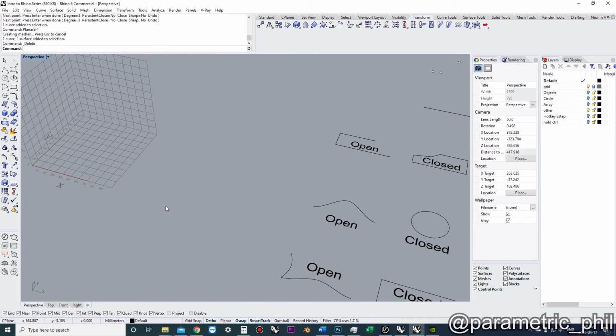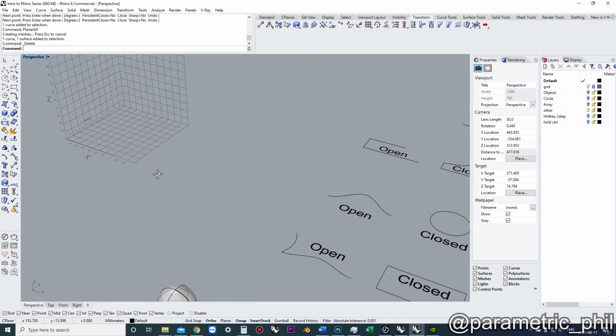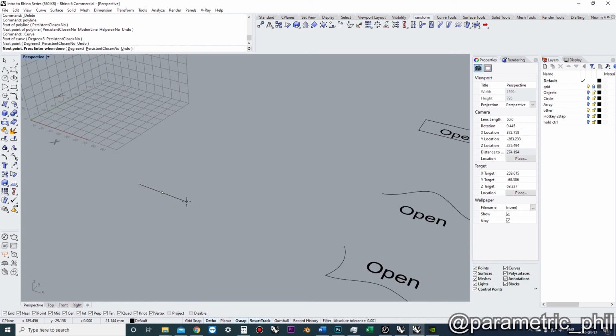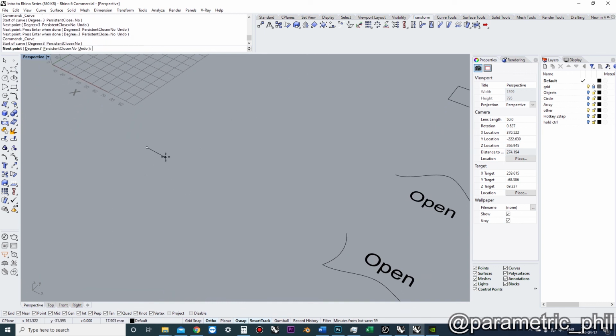And a little bit more complex version of that is we can create stuff like lofts. So a loft is an example of where we're actually using a control point curve, or we're using any type of curves to generate a surface in between two curve segments.